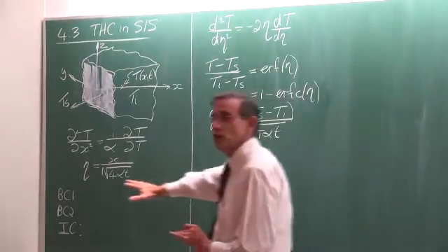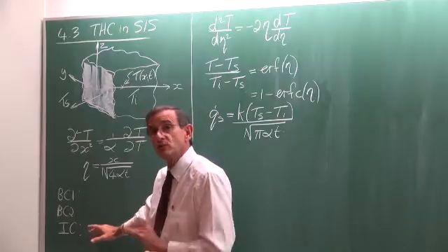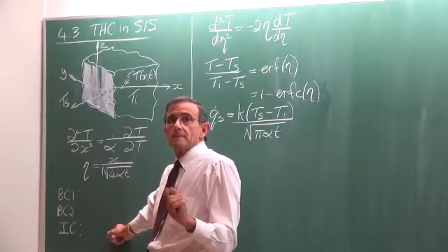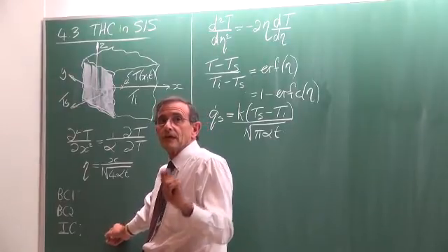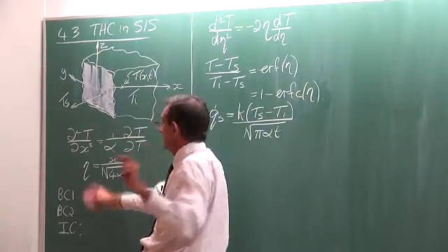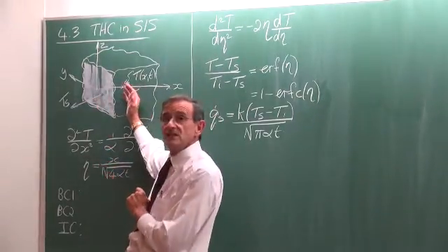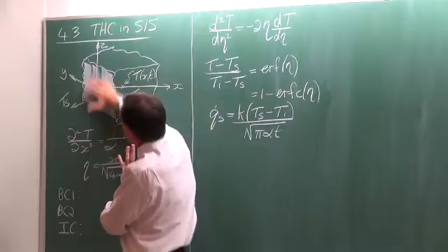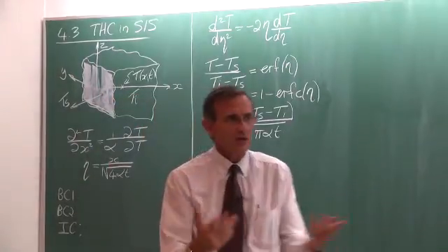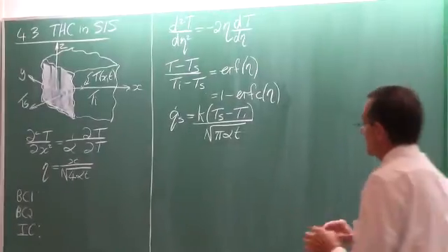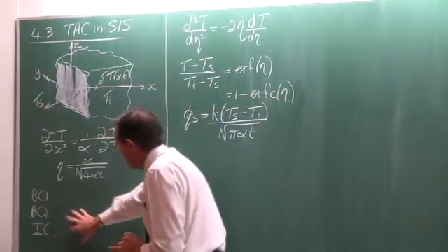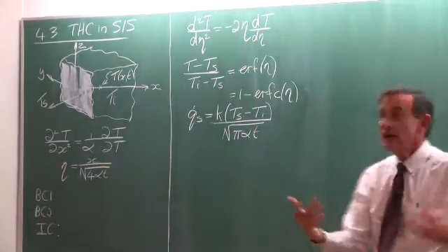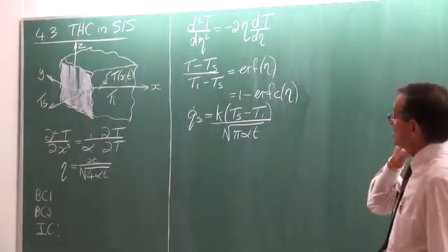Okay. Obviously, there are boundary conditions. And in these boundary conditions, what we need to cover is that the temperature, when t equals 0, is everywhere equal to Ti, except at the surface, where the temperature would be equal to Ts. So those are the boundary conditions, and we've discussed it. Now, these boundary conditions have to be written in terms of this format before that equation can be solved, and the result of that is we get an equation like this.